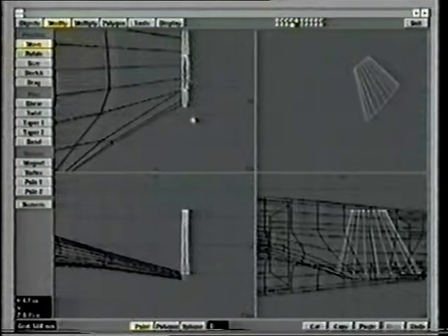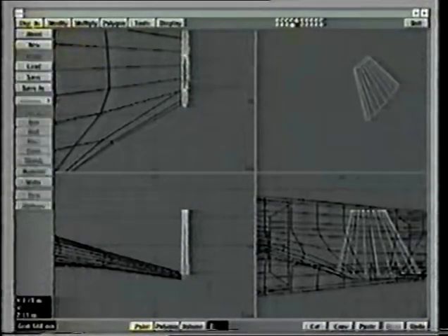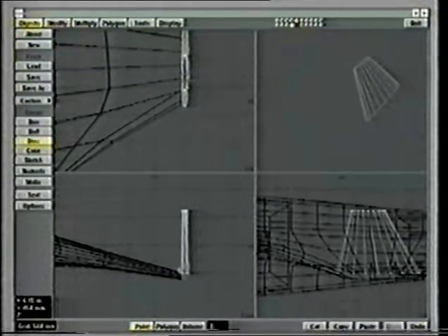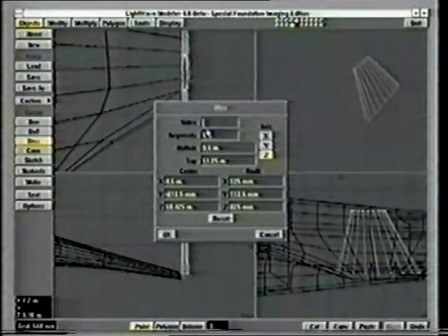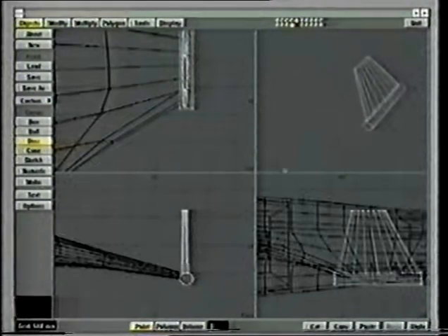Now, what I want to do at this point is move in a little bit and create whatever would be joining this wing tip fin onto the wingtip itself. So again, I'm going to use a disc, center it up there, and numeric, this probably only needs to have about 12 sides to it. Make that there. Okay, we've got a cylinder there.